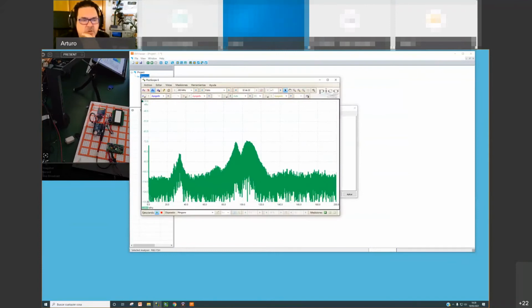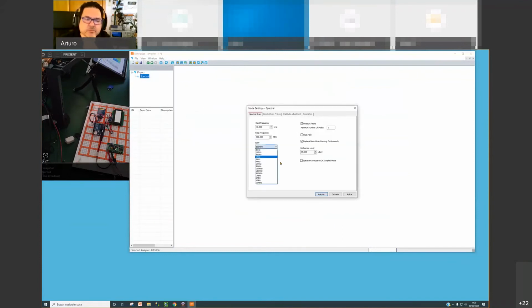Okay, so let's select the resolution bandwidth. Let's go to 120 kilohertz. A very small resolution bandwidth means a slower sweep for the scanner, or for the spectrum analyzer, really. But the idea is that with a smaller resolution bandwidth, you have more resolution in frequency. The idea of measuring peaks is to be able to identify from these measurements a number of peaks that are the most important.